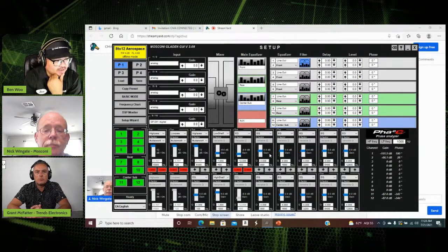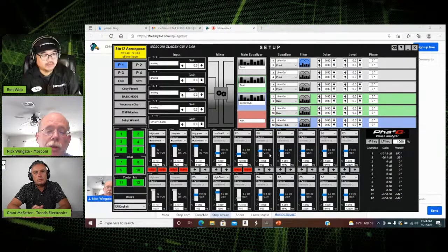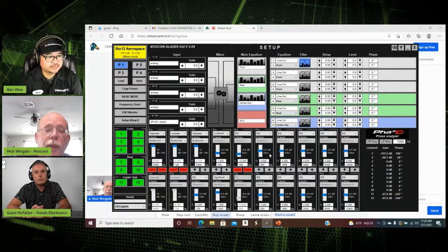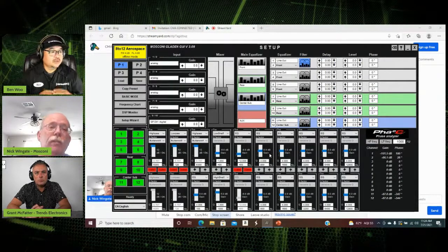Is that always the fix? Playing with the Q? Yes, it's always the fix. Okay. I will start with a Q of 4, Ben, and if I'm noticing it's affecting too much information, I will double it. I'll go from 4 to 8, then 8 to 16.